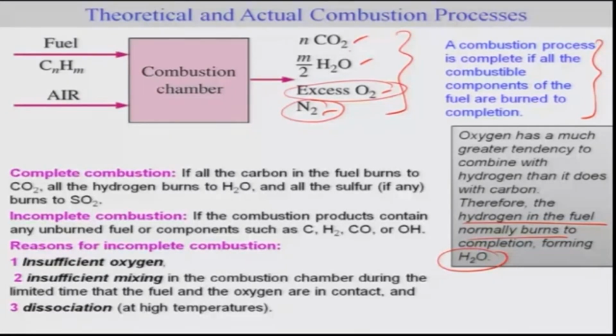Let me go through the definition of complete and incomplete combustion. Complete combustion is when all the carbon in the fuel burns to CO2, so that means CO2 has to be present, and all the hydrogen burns to H2O, and all the sulfur, if any, burns to SO2. Now we are quite well aware that SO2 and CO2 are not good for the environment. But this also means that reduction of the carbon and sulfur in the fuel is critical to have a better, more environmentally friendly fuel.